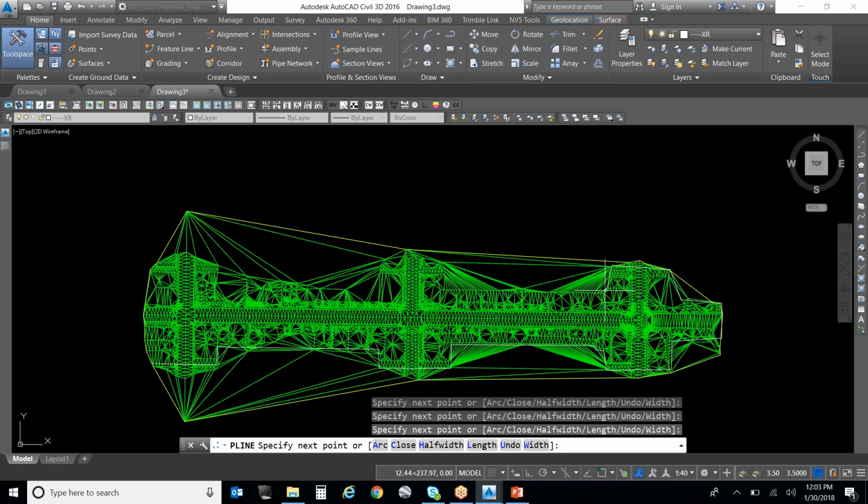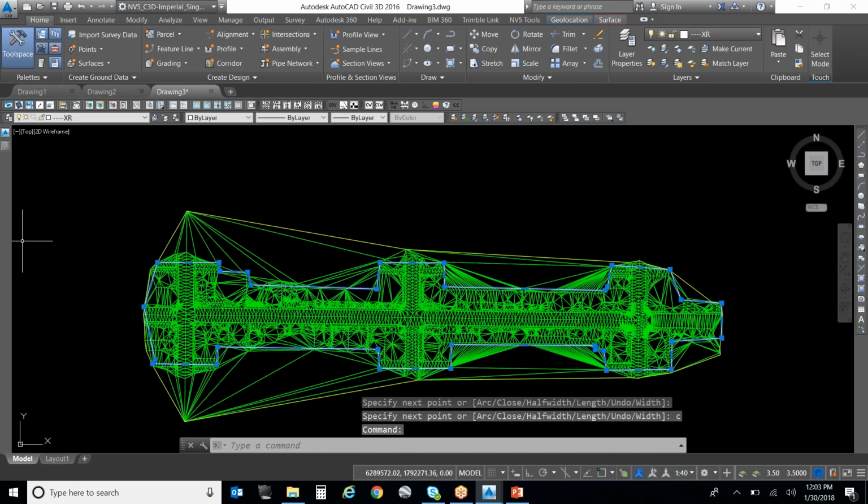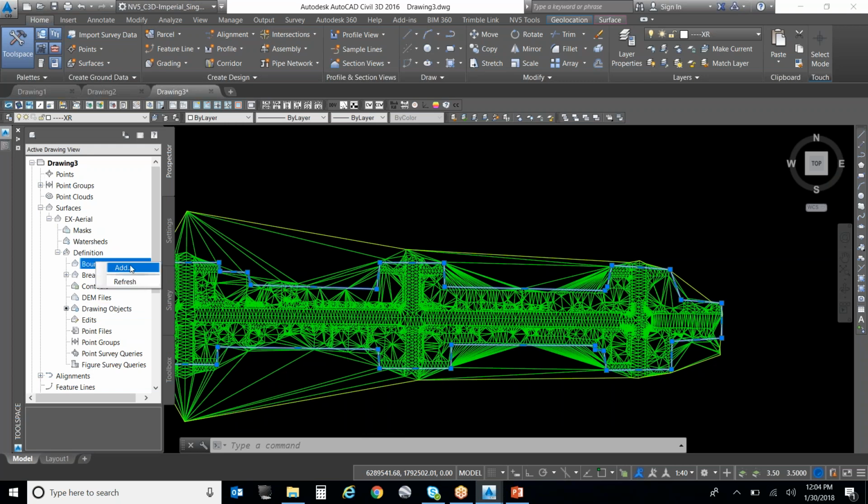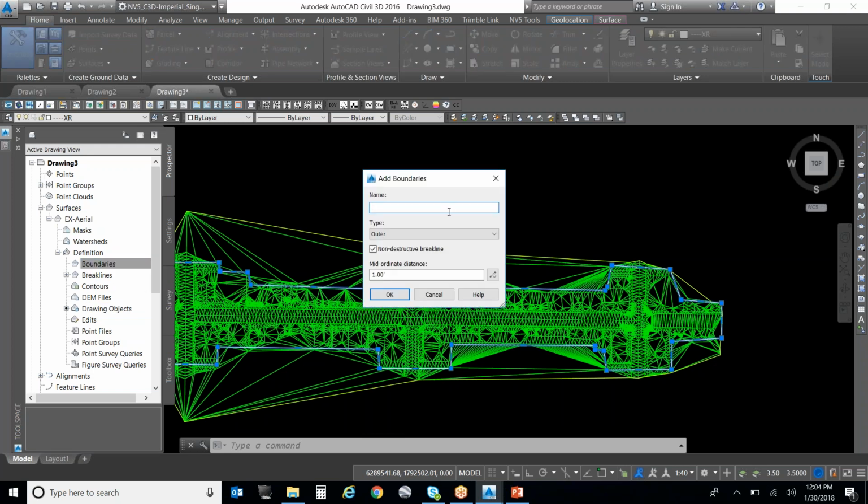The one benefit of doing that is if you get those arbitrary points that are like 0, 0, 0, you can't really tell sometimes just by looking at the plan view. So the other thing that you should do, in addition to doing a 3D orbit of your surface and looking at if you have any spikes or dips, is also to go to your surface properties under the last tab, not analysis, statistics. It will show you some information on your surface. One of the most helpful things is it will show you the maximum elevation and the minimum elevation. And you can actually change in the definition too to ignore any values less than 1. AKA if you have something on 0, you can eliminate it without having to do an edit. You can just tell it to do that in the surface.